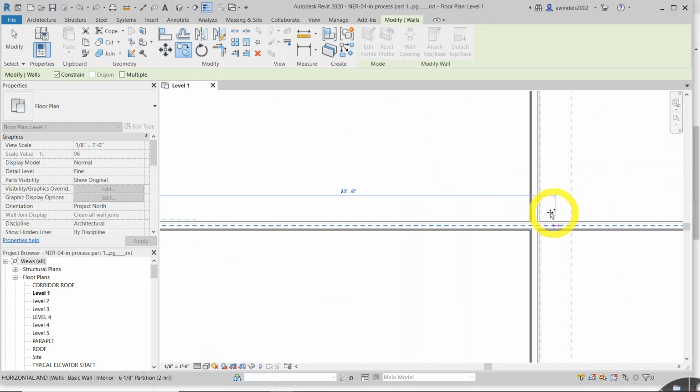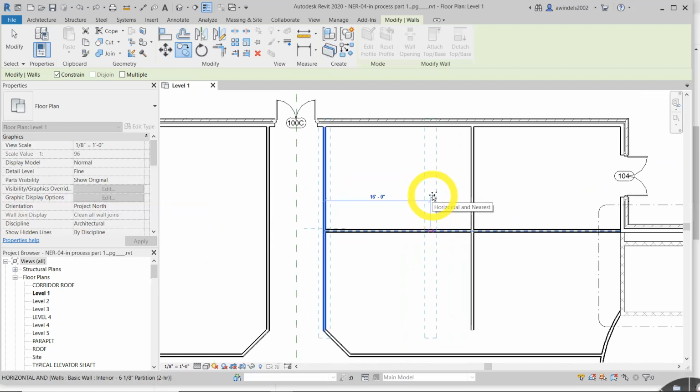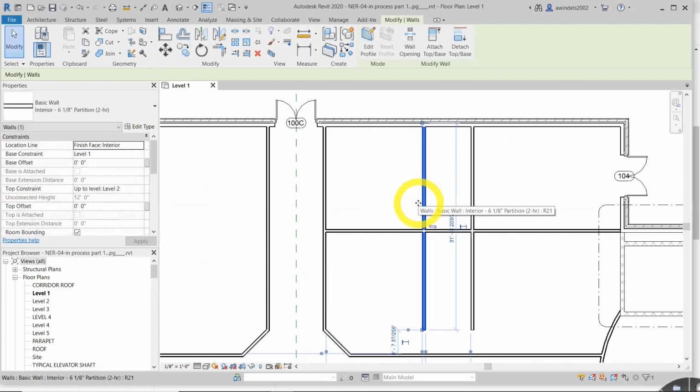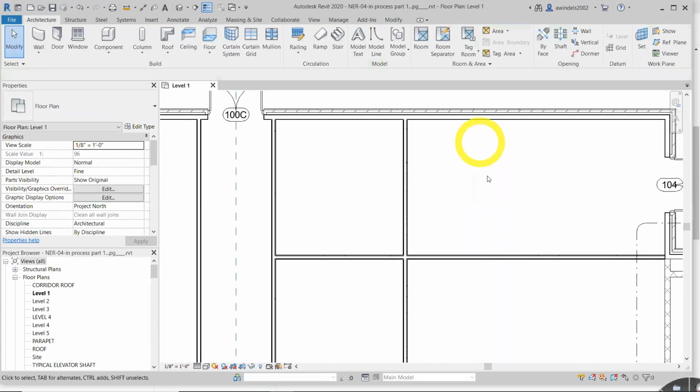Yeah, I already have the walls. It's trying to tell me to copy in this file, but just bear with me here. We're basically copying this one that's already existing there. That's why it's kind of throwing me off, but let's just say I want to copy another one and it's constrained. We'll say 15 feet, hit enter. Okay, and I just copied it exactly 15 feet from here to here. On this one, it was saying, let's just pretend it's not there and say delete.